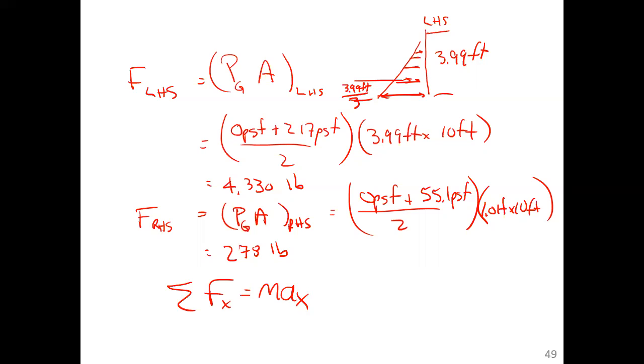This is where it all started. We started with this differential cube. And instead of statics, where we said sum of forces equals 0, with acceleration fields, sum of forces is mass times acceleration. So if you actually go through this, what you would see is that m times a_x is the density of oil times the original volume, which you know, 2.5 feet high by 20 feet long by 10 feet wide.